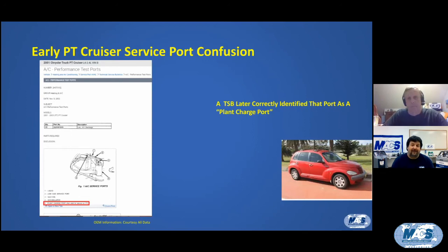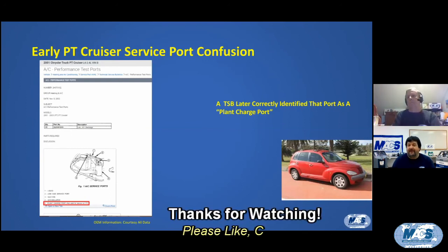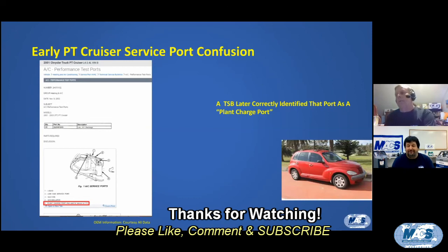Wow. So are there any vehicles that have only one service port? Yes, there are. I can't give you specific models right off the top of my head, but I can remember that there were some European cars. Audi is one that comes to mind that only had one service port. Wow. Yeah, the reason I'm asking is because I worked on a Jaguar recently. I looked all over the place, but all I could find was a high side service port. So the low side port might be somewhere, but I couldn't find it.